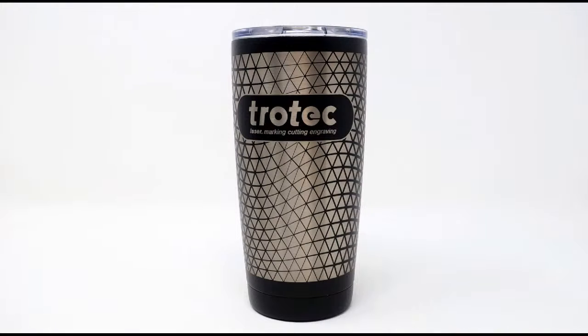And then the height would be how big of an area you want on the cup. Then go ahead, focus onto the cup, making sure it's perfectly level, and then engrave 360 degrees around it. The hard part in this case was waiting for the cup to engrave, because it takes a lot longer to engrave around that. So sometimes it's not so practical because of the time it takes to run, but if you ever do want to do this process, that is how it's done.